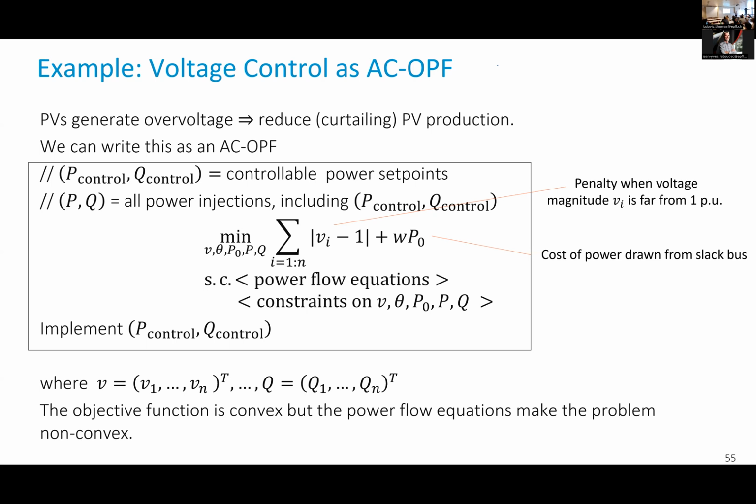That's a brute force approach. It's very primitive. Some operators in Switzerland, of course, pay you: they estimate how much they've curtailed, and you're paid for the generation that you have not generated, because the operator finds it less expensive to pay you for the power that you have not generated than to pay for another solution that would not dump any power. The other solution would be, for example, to put a battery somewhere in the grid and absorb the power into this battery. Many grids do that, but if you have just a few nodes that generate overvoltage, and that happens only a few days in the year, then you pay a few thousand francs a year to those customers for the power that has been curtailed. It's cheaper than to maintain a battery.